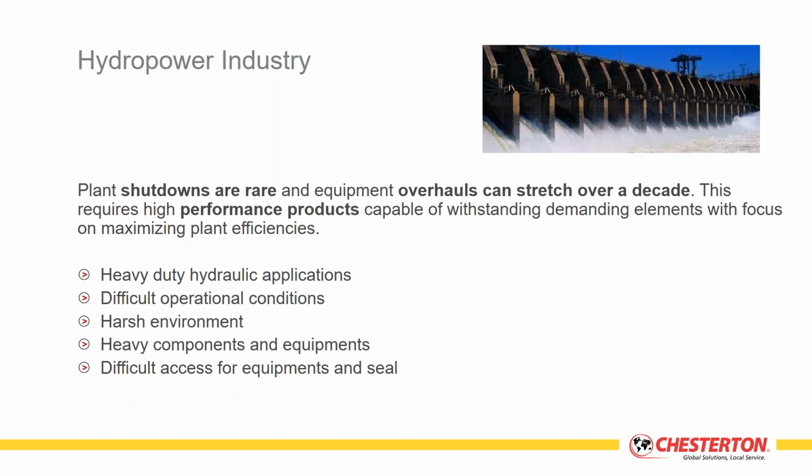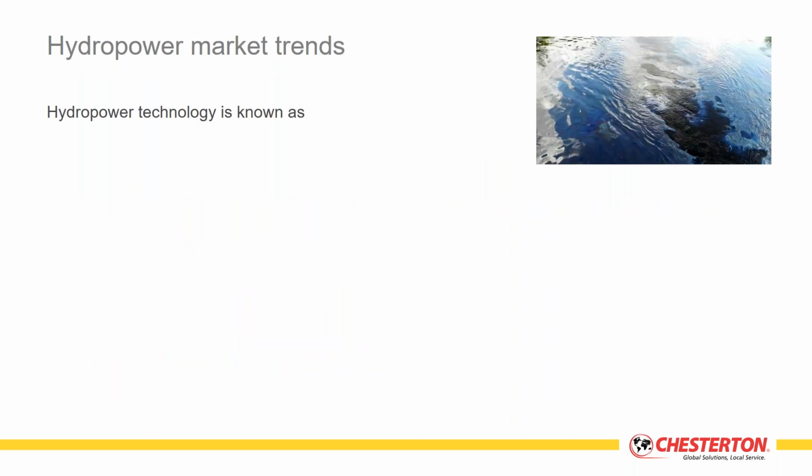So it means that even just a seal replacement could be a real problem and could take a long time, meaning that the time for the repair is relatively long. And erosion, corrosion, plus vacuum, which we have to take into consideration in most hydropower applications.